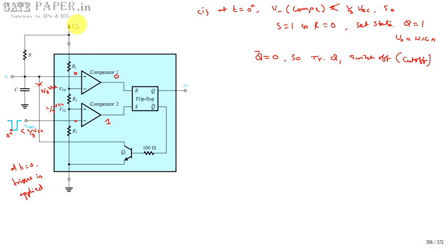Okay, so there is a chance that the capacitor can charge as the current is coming in this direction. Previously also current came in this direction, but since it was connected to ground as the Q1 transistor is on, current flows in this direction towards ground.